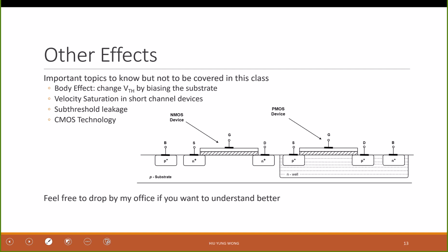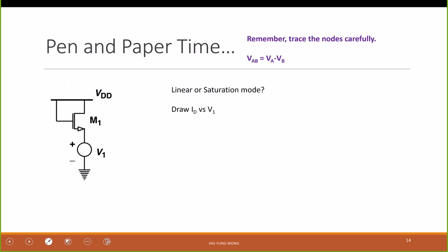And now they need the system level to control the chip. What they do is when this part is not working, they turn it off. What we call dark silicon, and only turn on other parts. So in your iPhone, not every transistor in the chip is working at the same time. Okay. And of course, we only talked about NMOS and PMOS each time, and they can be combined together to become CMOS technology, complementary metal oxide semiconductor, that you need to know, right? Yeah, so feel free to discuss. I claim myself, I spent many years in this area, so I should know this, right?